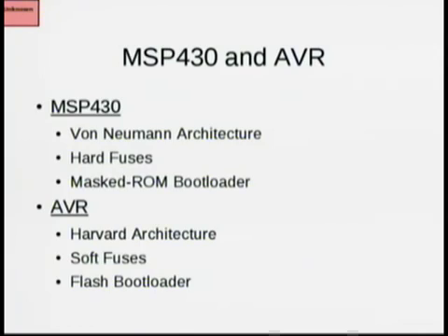This is in contrast to the AVR, which is a Harvard architecture chip. So you actually have 2 separate memories, one being flash ROM and the other being RAM. And a pointer might refer to one or the other. The only thing that specifies that is which instruction you use. And these are exploited differently. You can't write a simple stack overflow exploit for the AVR because you can't execute RAM.